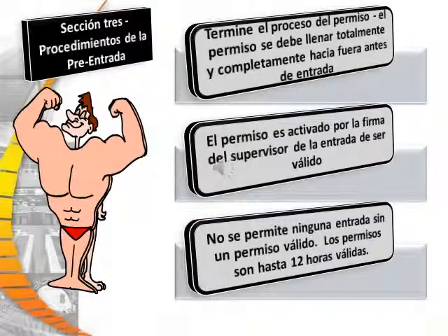Complete the permit process. The permit must be completely and fully filled out prior to entry. The permit is activated by the entry supervisor's signature to be valid. No entry is allowed without a valid permit. Permits are valid up to 12 hours.